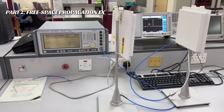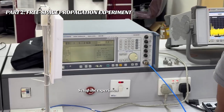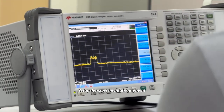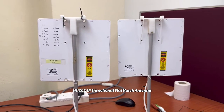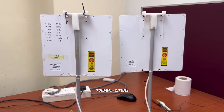Part 2, Free Space Propagation Experiment. For this experiment, we set up the measurement equipment to study free space signal propagation. Two identical antennas are used for transmitting and receiving. Both antennas are HG2614P directional flat patch antennas, which operate from 700 MHz to 2.7 GHz.